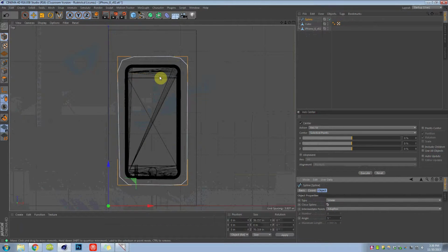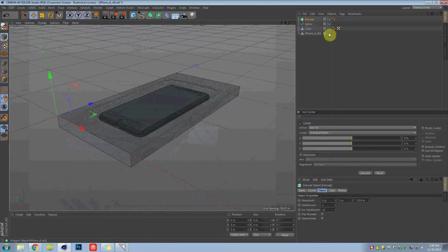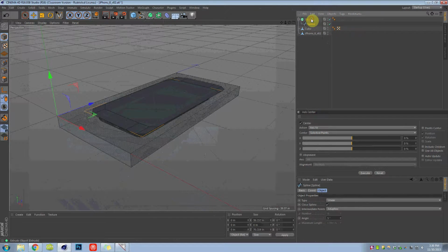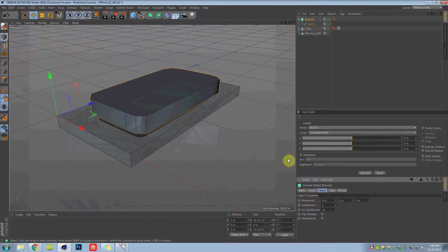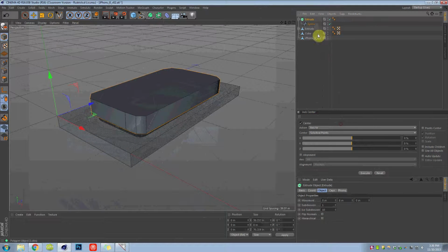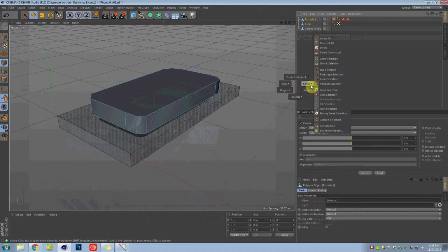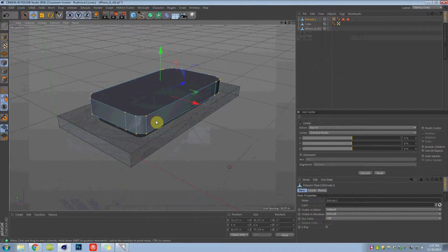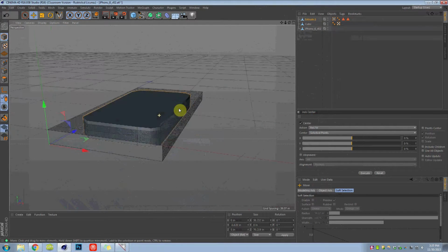There it is. Now that doesn't do anything on its own, so we're going to extrude that spline by dragging the spline into the extrude deformer and making sure that it is extruding in the Y direction. This is X, this is Y, this is Z. It needs to extrude more than 6 inches because it's cutting through the foam. So now select the whole thing, current state to object, connect all those and delete them. And I like to optimize the points, probably not necessary. But now, let's drag that down so you can see it's popping through both sides.